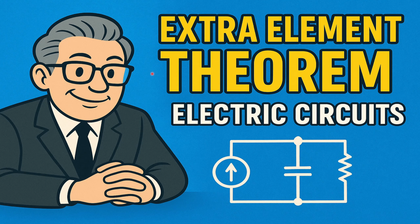In this example I will discuss a very important theorem called the Extra Element Theorem, developed by Professor Middlebrook from Caltech. This theorem is very useful if you want to develop or present your transfer function in a nice way where you see the poles and the zeros directly. In this case we will specifically use it to determine the transfer function for an RC circuit. It can also be applied to other circuit analysis.